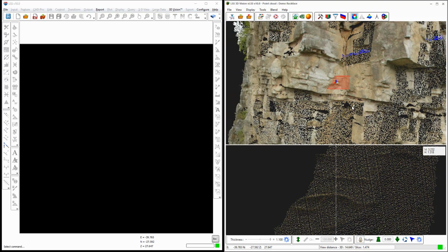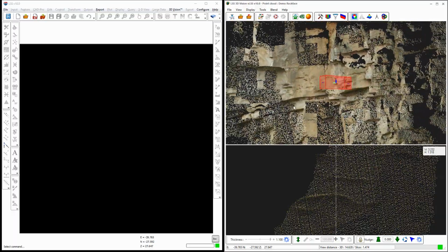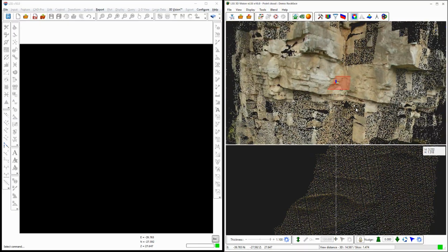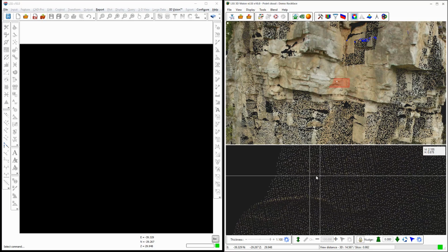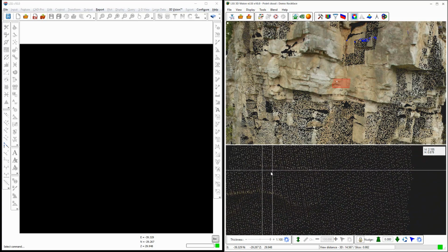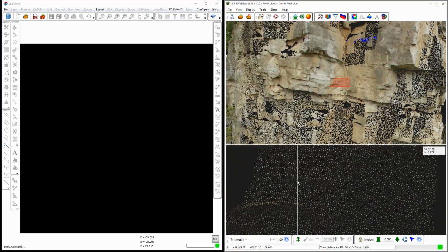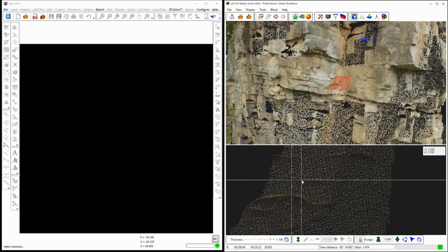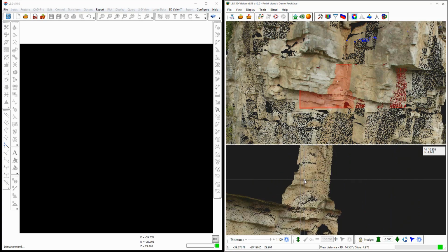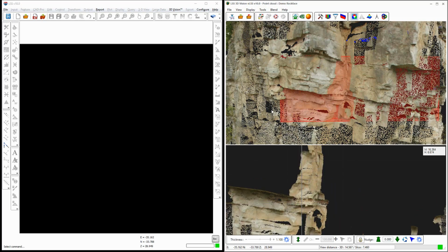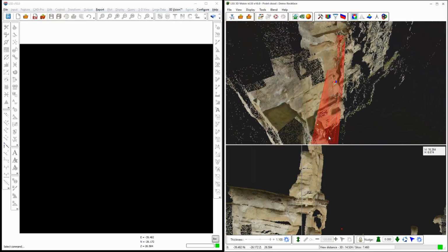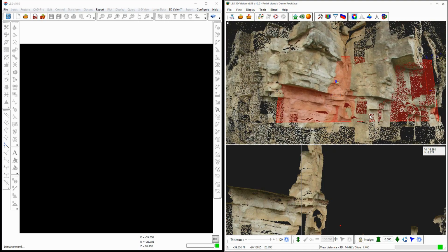That now locks the orientation of the slice, so when I move the 3D view around, the slice stays at the same orientation. What it will do, however, is allow me to move it. So I'm clicking and dragging with the mouse wheel in the slice view window, and you'll see the representation of where it is in the 3D view. And scroll out means I'm seeing more in slice, and therefore the box is getting bigger in the 3D view because this area is covering this area inside the 3D view. But because I've locked it in position, navigating in 3D isn't changing the orientation of the slice.